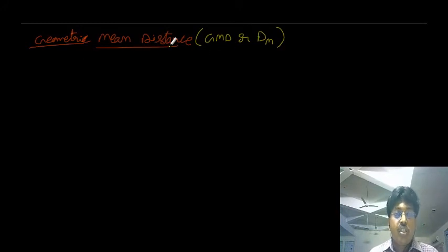Geometric mean distance is the geometric mean of distances between conductor A and conductor B. Each conductor's geometric mean distance is the geometric mean of distances of each strand of conductor A to each strand of conductor B. That is, GMD is the geometric mean of distances between each and every strand of one conductor to each and every strand of the other conductor.